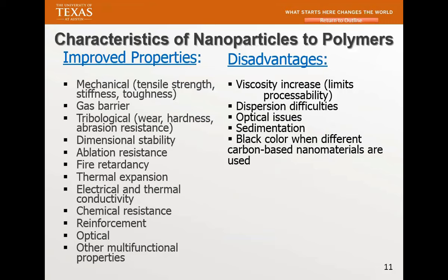You put a little bit of nanomaterials in there, and your thermoset is so viscous. If you're using it as a resin and put it in the fiber, you cannot process it. Then you lost the processability. And you may say, I have a very good nanocomposite, but I cannot process anything. Well, that's useless. So you really need to think about viscosity.